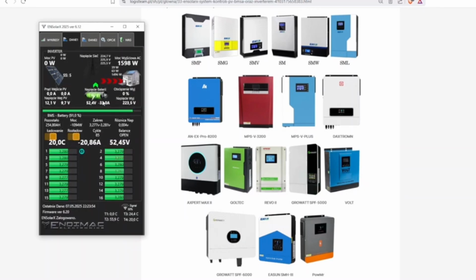Do you see this upper slider? It shows how much we have this output controlled now, and it automatically regulates itself. So you see, I have it controlled now to 2,260, and because I allowed it to give a maximum of 30 amps, it oscillates within these limits. It already has 32 amps, so it has seen that it has a little too much. So it has reduced it to 28, and it should add a little, and it will be floating somewhere within these 30 amps.